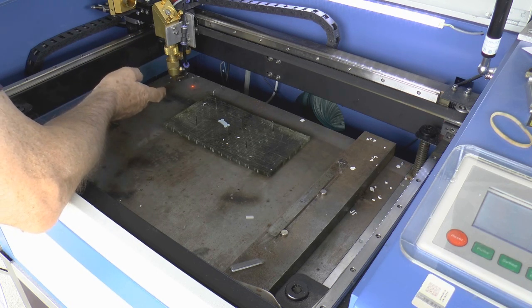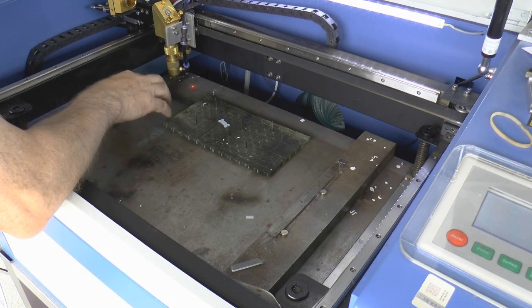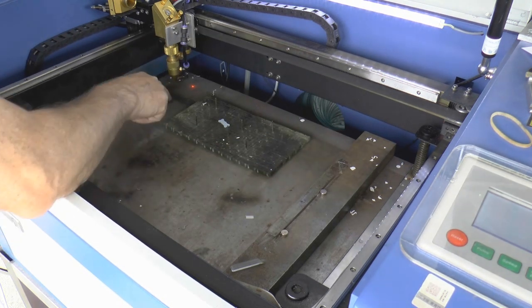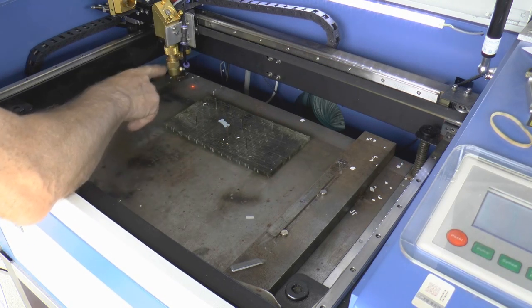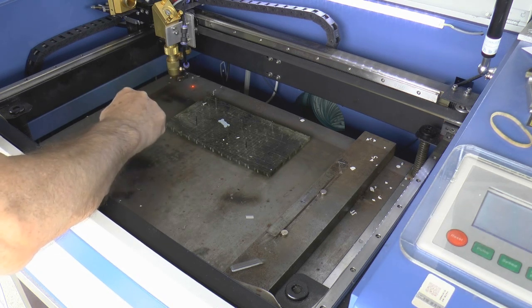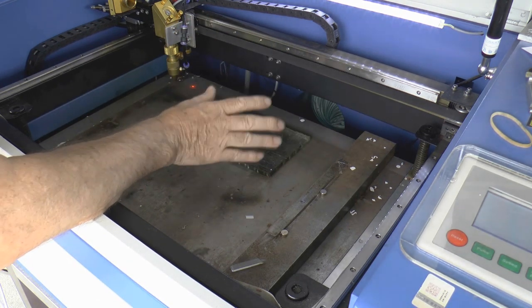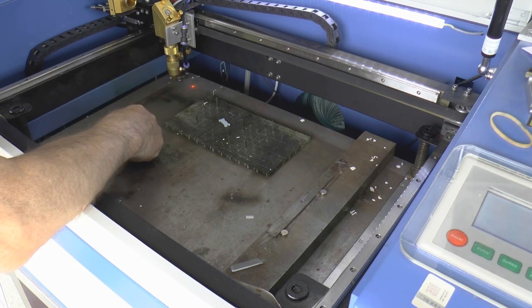So, you know, the only questionable one as far as I'm concerned is anchor point. And I believe that the anchor point is the one where the program 0 is stored within the program itself, so that whenever you come back and run the program, it will start from the position that you set within the program, i.e. even if it's 00 now, it'll jump to the last anchor point that you left in that program. And provided you don't take it out of the machine, that program will hold the 00 for the program. And that's the whole point of something called an anchor point.